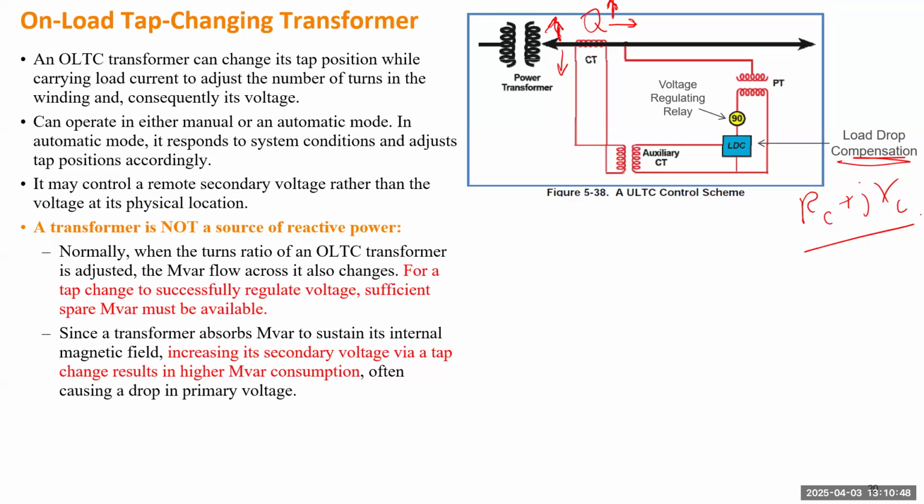So if the operator believes the primary side on the left-hand side is not strong enough, you need to disable this control manually, or you have some other algorithm to decide when to disable the tap changing transformer. So the tap changing transformer under normal condition does give you voltage regulation, but under emergency condition, it is usually the first thing you need to disable under voltage stability concerns.